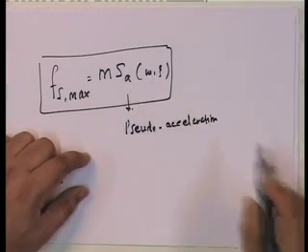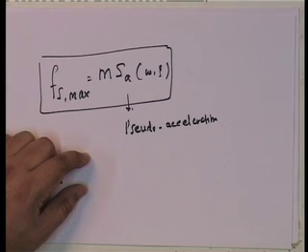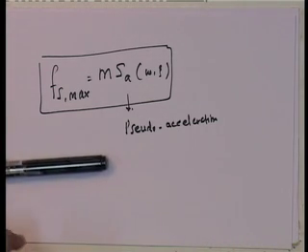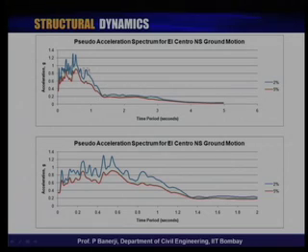and if you draw it with respect to omega or t, okay, then this is what it looks like. If you look at the pseudo acceleration spectrum, this is what the entire thing looks like. Okay. There are certain interesting things about this. Again, the same thing, this is across all time periods, and this is where you have taken the peak one and shown it, blown it up and shown it here. So, this is the same thing, excepting that I am really taking this part and showing it a little bit larger. Okay. And this is something very, very interesting, and that is that the acceleration has a specific role to play. Note that this is the pseudo acceleration spectrum, across time period for different values of xi.